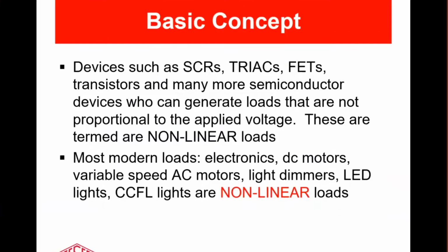So devices such as SCRs and triacs, FETs, diodes, all of the semiconductor devices which basically control our world today, these produce loads that are nonlinear, and one of the ways that we discuss and analyze these loads is through the use of harmonics.